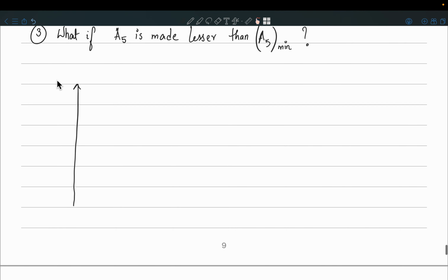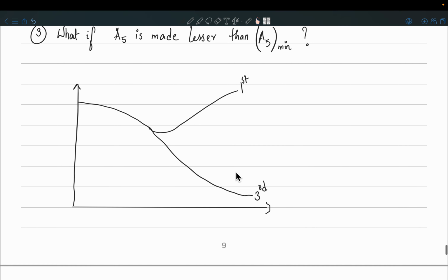Okay, so we had this. This is the X location along a converging diverging nozzle. Okay, simple CD nozzle. And we had the pressure ratio. So initially the pressure starts declining and then it increases if the flow is subsonic, and then if I keep decreasing the pressure, this was the supersonic isentropic case, which was my third critical. This was the first critical, and the second critical was if at the exit I have a shock. So this is my second critical.